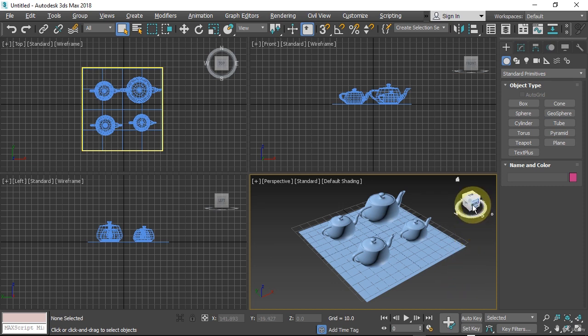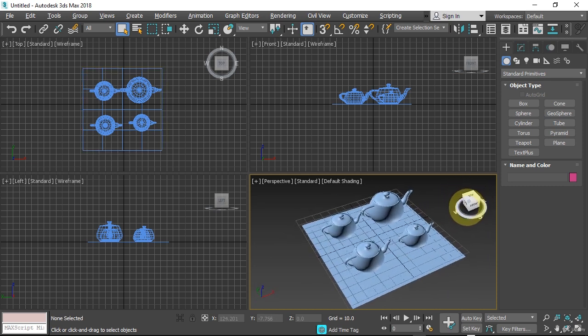If you are using the view cube, which is this transparent cube at the right top area, you need to move your mouse first to the edge of the viewport like this, which takes more time to perform. And also, if you are using the navigation tools down here, you will need to move your mouse even further. These two methods can still be useful in a situation where you couldn't find a standard 3-button mouse, and so you are forced to use your laptop trackpad, for example. Other than these scenarios, it is recommended that you use your mouse and keyboard combination to navigate the viewport.